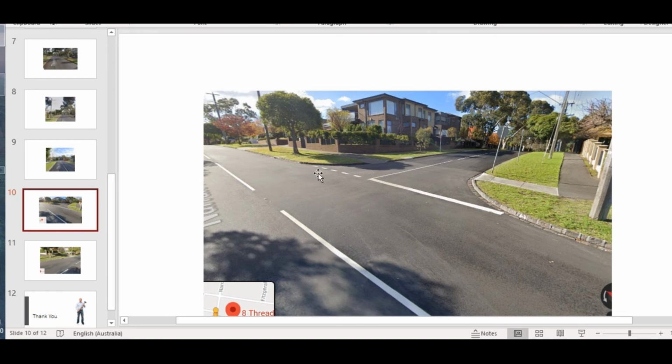So in a nutshell, for example, there is a connection, making sure that there is a center line, and a stop line and dotted line. We make sure that they align the center line here, both aligning very well with each other. It means that we have the right filling when we do construction, making sure that the radius of the curve is easy when the vehicle accelerates, stops here and then turns. It can accommodate that maneuver, making sure of the traffic signs, for example, here are stop signs. Why do we provide stop signs, why not a give way sign?